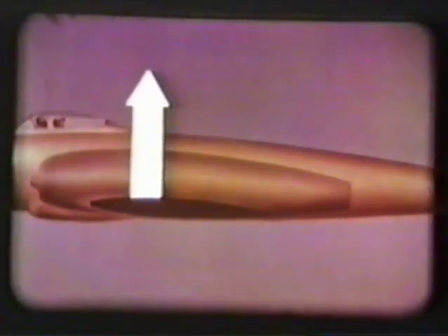Finally, the top shock also moves to the trailing edge, making the aircraft go more nose down again. Most aircraft don't do all of these things, but the center of lift always shifts toward the rear when passing through the transonic range. So all aircraft suffer a final nose-down trim change.